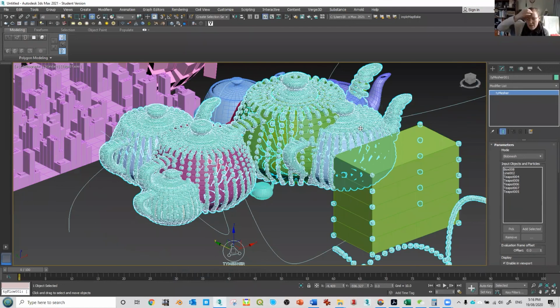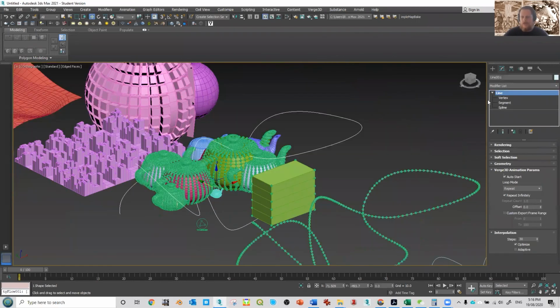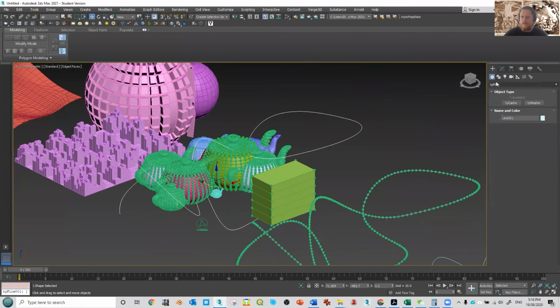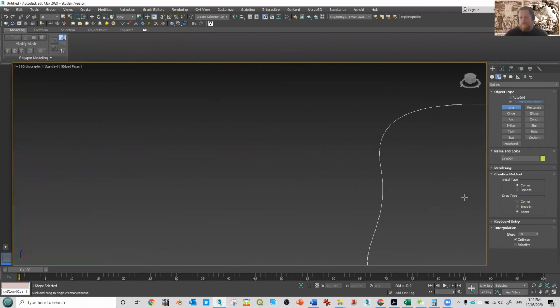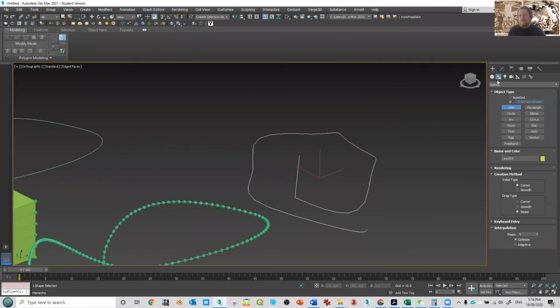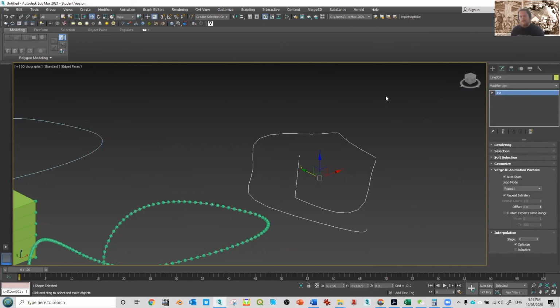I missed how you added more points on your spline. Yep. I might do it on a separate spline just to make it simpler. So when you zoom in, I think the default is 6 or something. When you go into your modifier, it used to be up here. It's the first thing, and it's usually hidden because, unless you're doing curvy stuff, you don't tend to tinker with it.